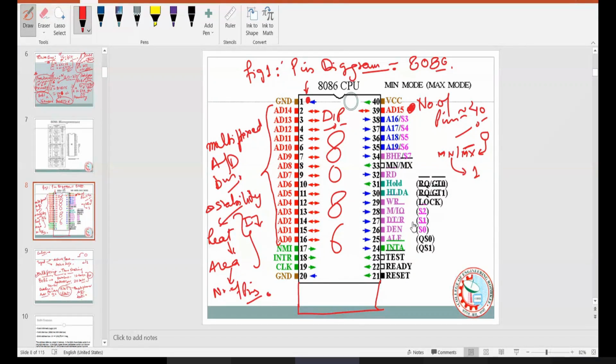Sir, how can we reduce the heat produced in the microprocessor? There are many ways to reduce the heat. Like if we talk about the latest processors, these days they are coming with gel pads on top of them, along with a very small fan over the microprocessor, bigger heat sinks, and very smart designs of heat sinks. These all are strategies to reduce the heat generated inside the microprocessor, because there is no way heat will not generate. If the processor is working, current will flow, and heat will generate. Definitely you can't avoid it.